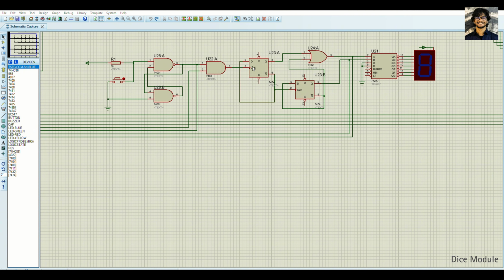The clock pulse is entered in the first D flip-flop, which gives the Q output logical 1 in every 2 pulses, serving as the least significant bit. And another D flip-flop does the same thing, taking the clock pulse from the Q prime of the first D flip-flop, serving as the most significant bit, thus giving us a smooth 2-bit up counter ranging from 00 to 11.